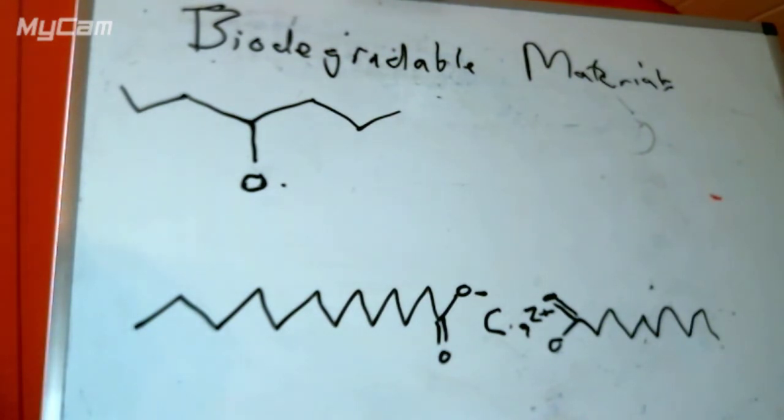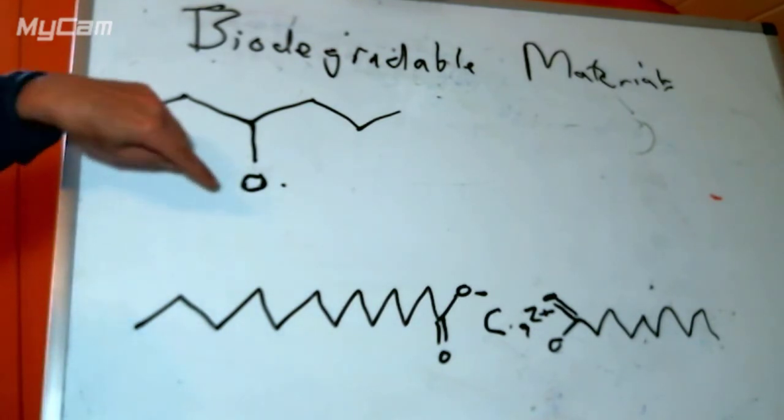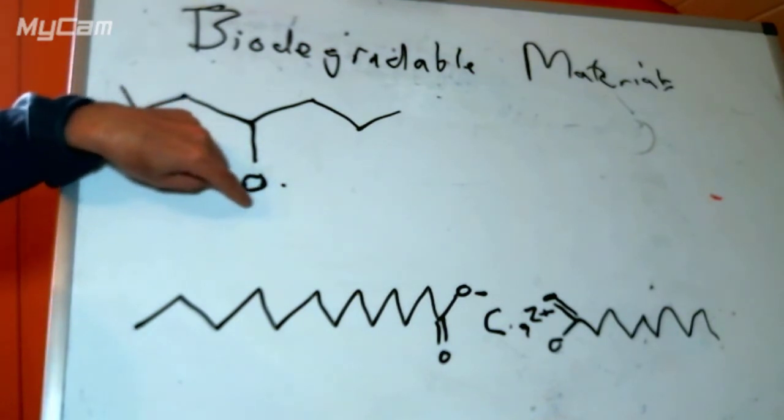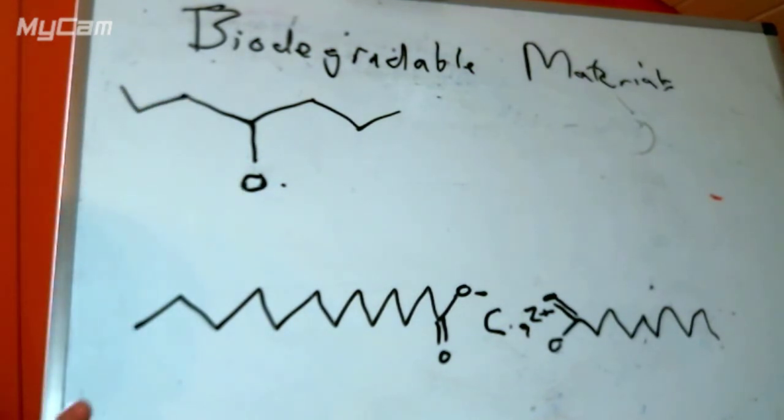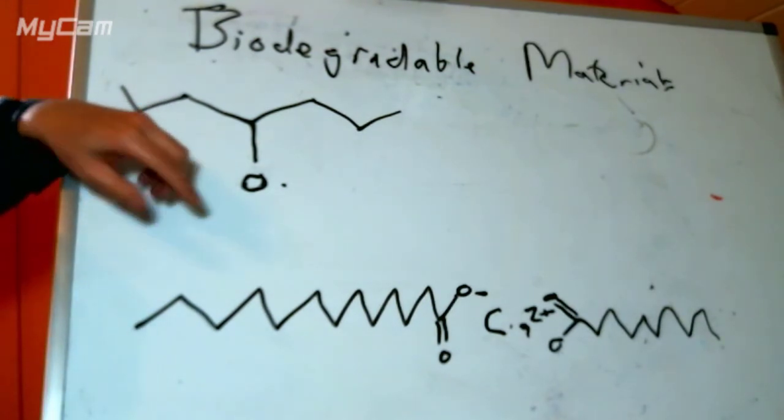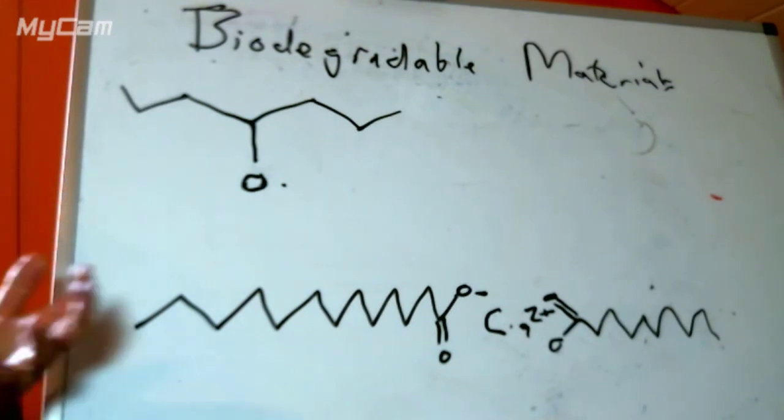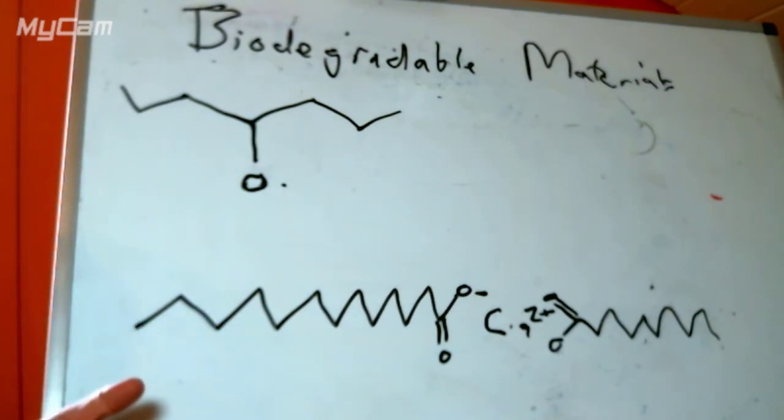If we deliberately make that pure with iron or cobalt, we can make a catalyst that will catalyze the radical formation in our polymers, and that will make the degradation of the polymer faster than it would be otherwise, because we're hitting the rate determining step. If we use a photocatalyst to make more singlet oxygen, then we will make more peroxide to start with, and that will obviously also linearly increase the rate of reaction, because if we've got twice as much peroxide, then the probability of one of them breaking is obviously twice as high.